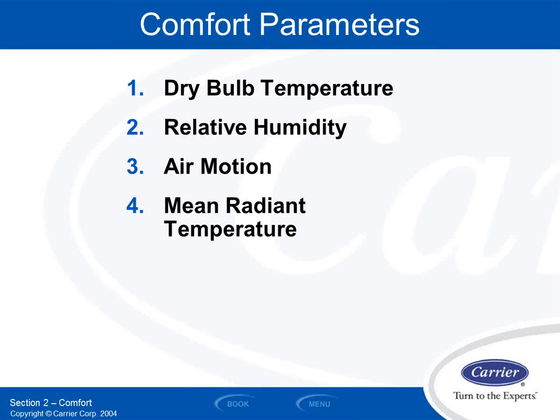about how they're interrelated. Wet bulb temperature means I take a thermometer, I basically stick it inside a wet sock, and then I take the temperature reading. And usually the wet bulb situation is going to be cooler than the dry bulb situation. I've got that evaporative effect, and we'll talk about how that works in a little bit today.